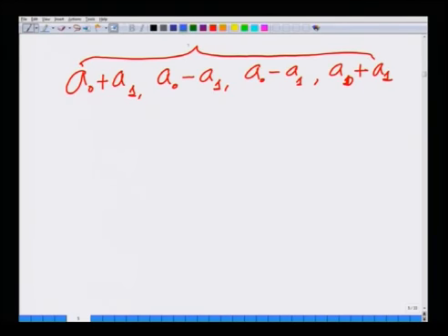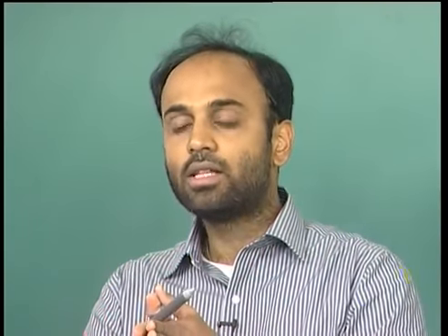This is the transmitted signal. So, I am taking the information symbols corresponding to the two users 0 and 1, multiplying them with their spreading codes, adding or combining these multiplied signals, and then transmitting them over there.